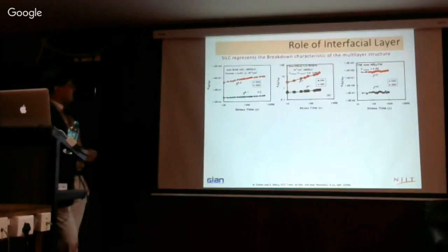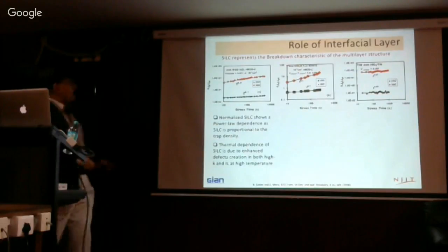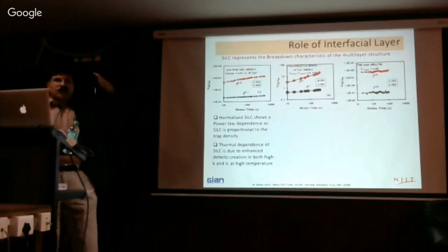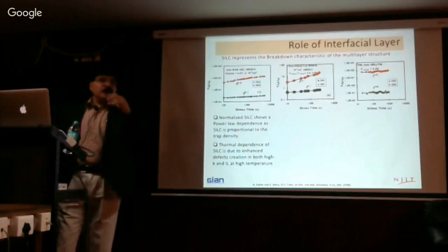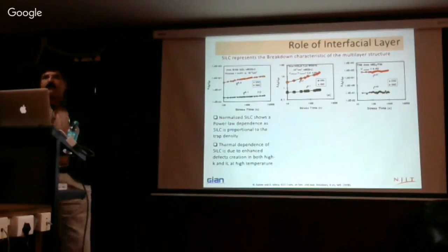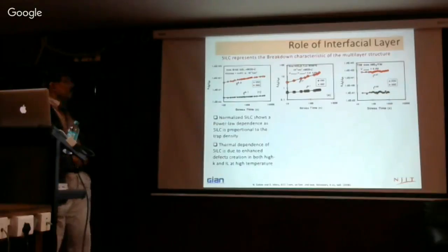This is actually only silicon dioxide. This is the combined one. So this still shows a power law dependence in there. Power law in the sense I will discuss the NBTI issue tomorrow. When you stress these things, depending on the defect creation, the increase as a function of time goes as t to the power n. That means the defects are directly created. There are a lot of different models out there, so we'll talk about that.